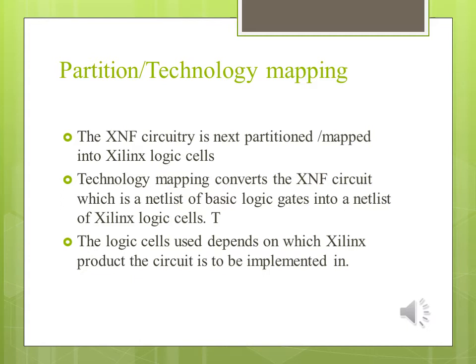Partition or technology mapping. The XNF circuitry is next partitioned into Xilinx logic cells, but a more common term for this step is technology mapping. Technology mapping converts the XNF circuit, which is a netlist of basic logic gates, into a netlist of Xilinx logic cells.